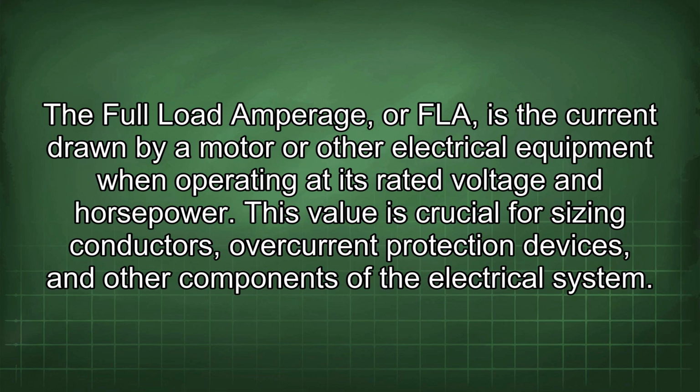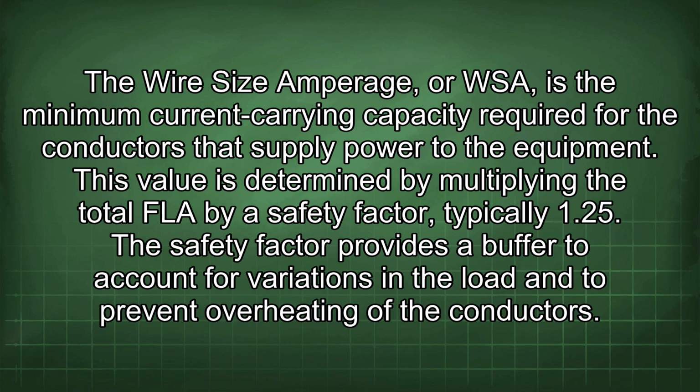The full load amperage, or FLA, is the current drawn by a motor or other electrical equipment when operating at its rated voltage and horsepower. This value is crucial for sizing conductors, overcurrent protection devices, and other components of the electrical system. The wire size amperage, or WSA, is the minimum current carrying capacity required for the conductors that supply power to the equipment. This value is determined by multiplying the total FLA by a safety factor, typically 1.25. The safety factor provides a buffer to account for variations in the load and to prevent overheating of the conductors.